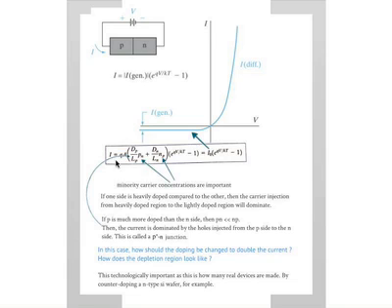But in any case, you can just calculate it based on the diffusion equation, as shown here. You can see the important points are shown here. The minority carrier concentrations are the important part because, again, it's the concentration gradient of the minority carriers. For instance, it is the electrons in the p-type and the holes in the n-type that give rise to this diffusion current. So, a few practical issues which are important here.